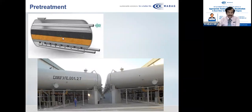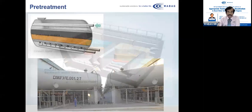So this system is very simple, and when your intake is quite good and the water quality is good, it is preferable to go for this system, because the capex is low and opex is also low, and it is very easy to operate and very simple to maintain. And where slightly more particle collection occurs, it is better to go in with air scouring to break the cake formation first, and then do the backwash following the air scouring. So this is very commonly seen in simple desalination plants.